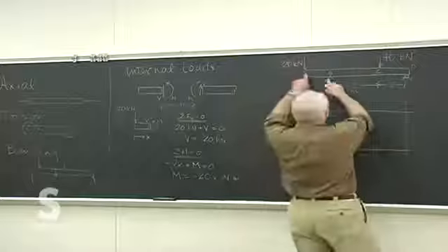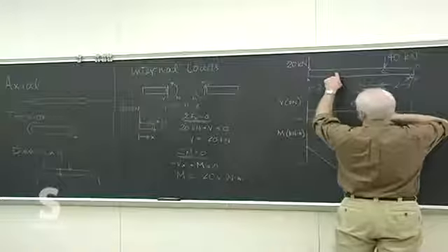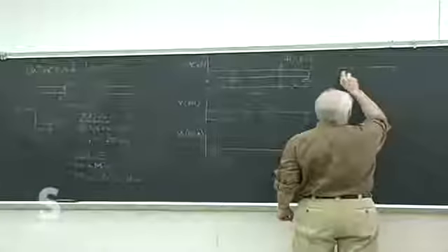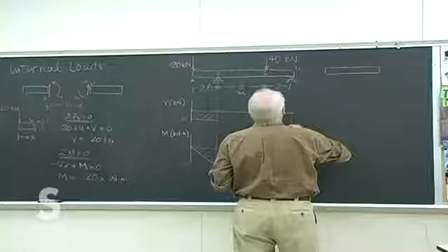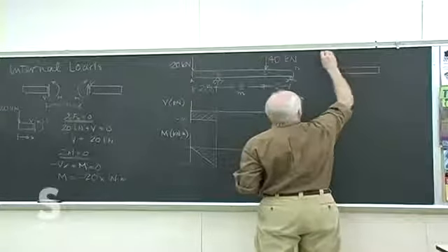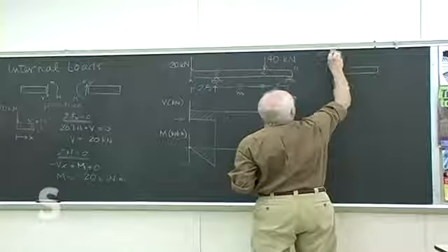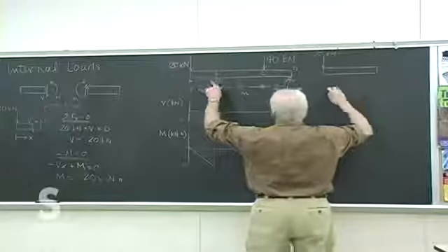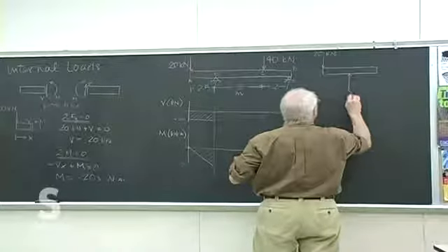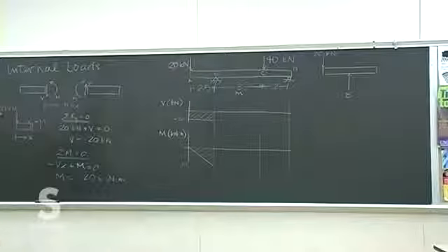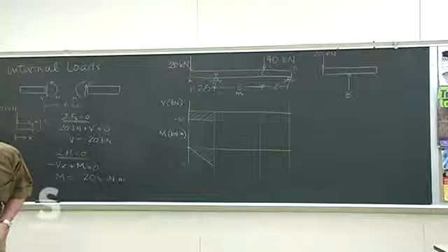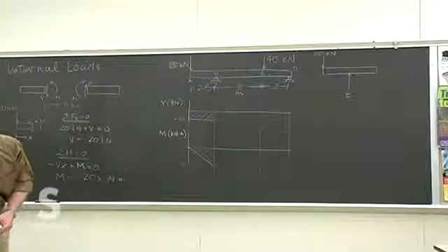All right, we can continue on. Nothing again changed until B. Once we get from B to C, we do have a bit of a change, so we draw out to there. We've got that load there, 20 kilonewtons. We now have one of the supports at 2.5, one of the reactions. That's a reaction at B. Oh, we didn't do those, so we have to figure out what those are, but that's a fairly quick matter. I'll put them in for you. You can check them.